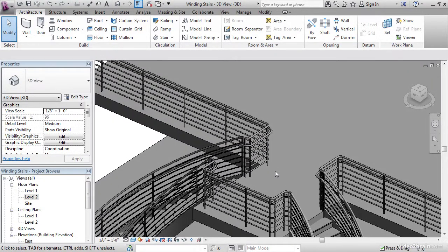It's getting too easy. All we had to do was start the railing command by selecting an existing railing and creating similar. We offset the railing in from the front of the floor edge by 6 inches. We also added some fancy radial edges to give the railings that special shine.